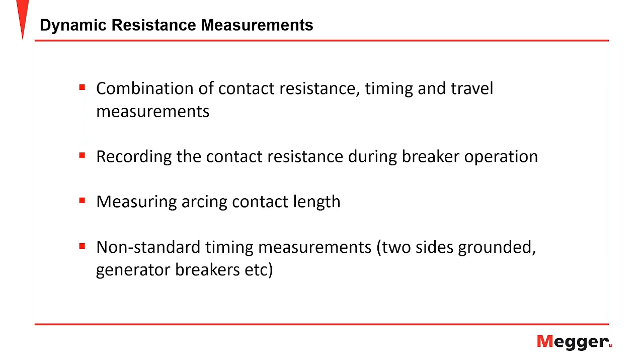If simultaneously you can record the contact movement, you can read the resistance at each point of the contact, and this method we use for contact diagnostic, and in certain cases it can also measure the times too.